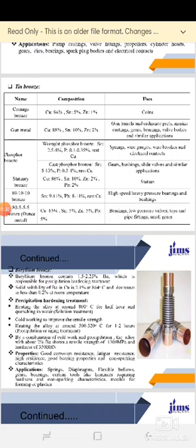Next we have gunmetal. It is very important, gunmetal, because it has come in the university exam also 2-3 times. The composition is copper 88%, Sn 10%, zinc 2%. It's used in gun barrel and ordnance factory parts, marine casting, gear, bearing, valve bodies and similar applications.